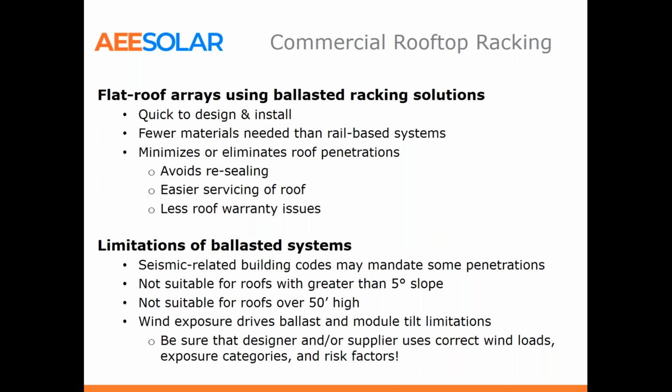It avoids resealing the roof and makes servicing the roof easier. If the roof ever does have an issue, you can just remove that part of the array, service that one portion of the roof, and not have to take off the entire array. We see much less roof warranty issues.